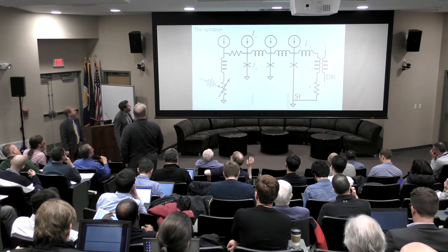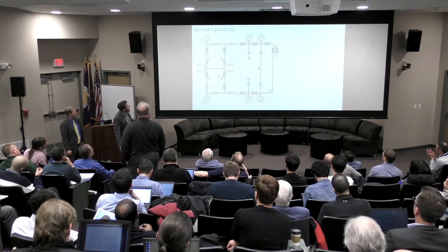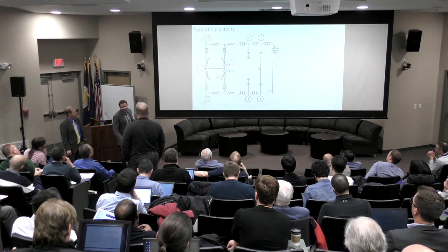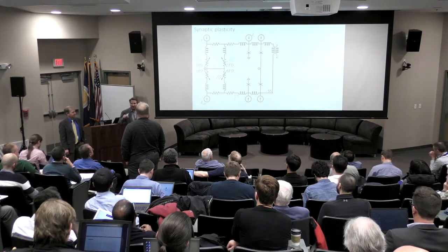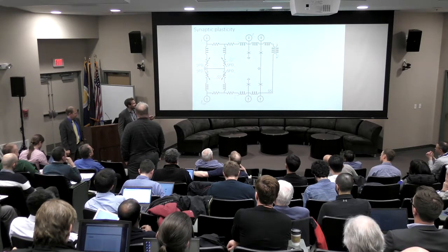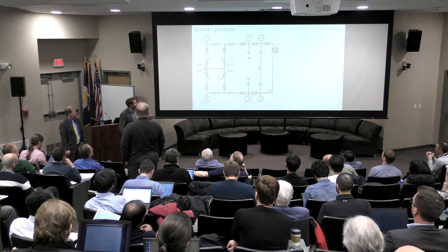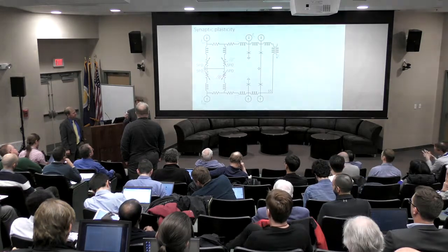So this is the synaptic bias current, right? You deliver a current right here to this Josephson junction. This circuit right here, if you see at its output, that is that synaptic bias current. It's a little bit nuanced, but basically, I picture it, all the synapses on one wafer are going to be fed by one main drive line that's going to mutually inductively couple to this same thing, and then you adjust it on top of that with this circuit right here through spike timing dependent plasticity. So basically what you have is one off-chip voltage source that goes down into the fridge. Then there's a resistor. The resistor is probably also out of the fridge, and that makes it a current source. And then on top of that, you're just fine-tuning through mutual inductors how much actually makes it to the synapse.